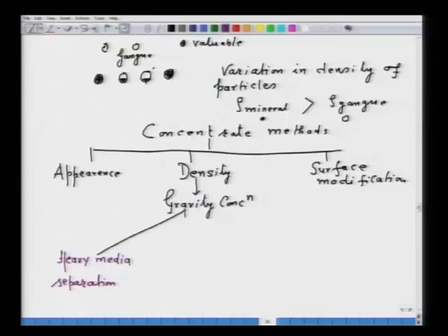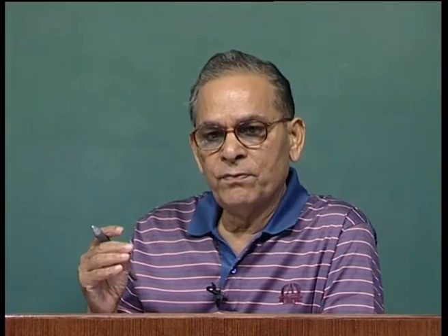Another method is called classifier, where air can be used as a medium or water can be used as a medium, and where the velocity of fall of particle is used as a separation, and that is different in air, different in water. So, accordingly you have pneumatic classifier or you have hydro classifier. In hydro classifier you use water as a medium, in pneumatic classifier air is used as a medium, and the difference in density is the key concept of achieving separation of the mineral.